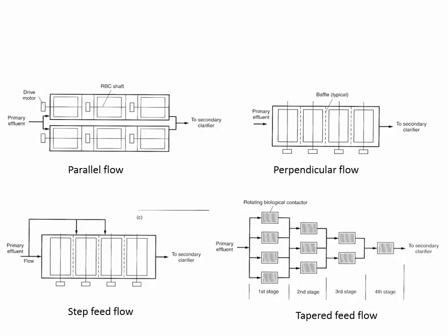When we were talking about reactor configurations, we talked about a perfect plug flow reactor, which is essentially a pipe, and if you have a little plug of some constituent that's reacting, as it travels through the pipe, the concentration is decreasing.